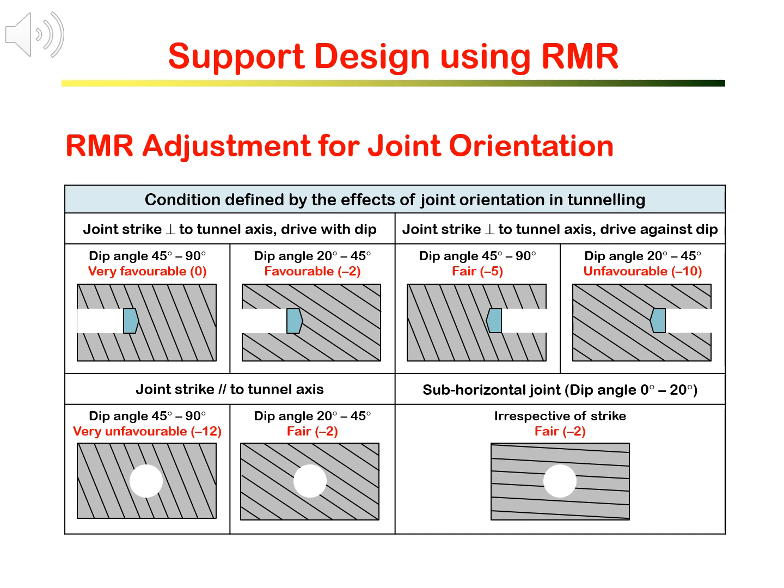I think from those diagrams, you can appreciate easily the effects of joint orientation on tunnel excavation. We generally can expect a smooth excavation operation when drilling or excavating the rock along the joint dip, but less smooth when drilling and excavation is against joint dip. Particularly when the joint has a low dip angle, drilling may be deviated by the joint. Overbreak may happen by blasting and cutting.